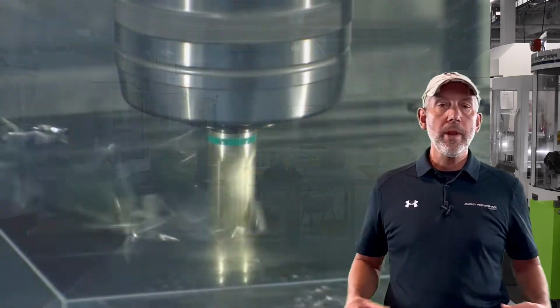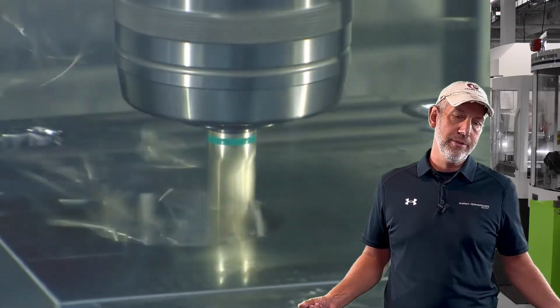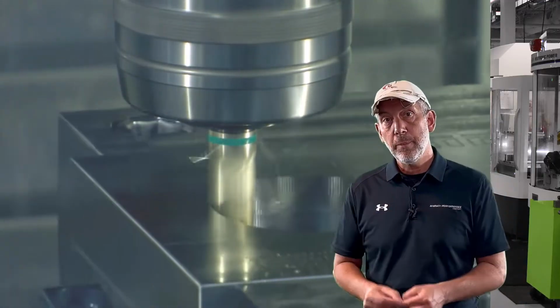What's the quality of my hole? I can't pick a drill. I can't choose a geometry. I can't look at all those things that a drill has to offer if I don't know what the quality of the hole is I'm drilling. Let's explain. First of all, if we just want to open up a pocket, drill a start hole, we really don't care what kind of drill we use. We just want to make sure it's big enough to put a hole in there.